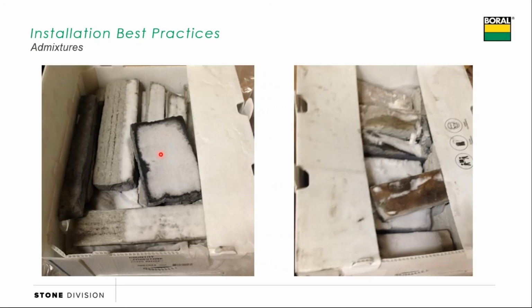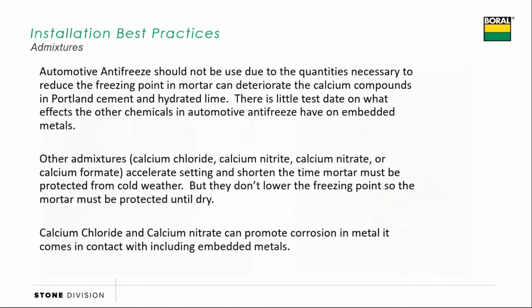Please don't use stones that have ice or snow or water on them, or even if they're dry, if that stone temperature is 20 degrees, they are not going to bond well and they're going to contribute to freezing your mortar. Please don't use antifreeze. If you're old enough to remember a time when we did, antifreezes have changed drastically since that time, and they now actually probably have a negative impact on your mortar.